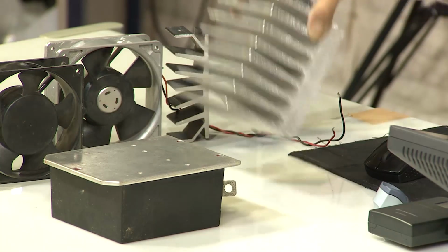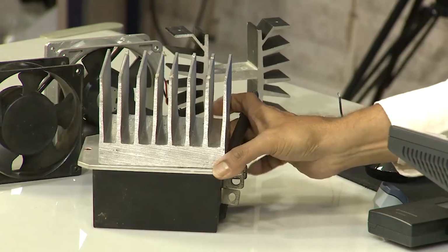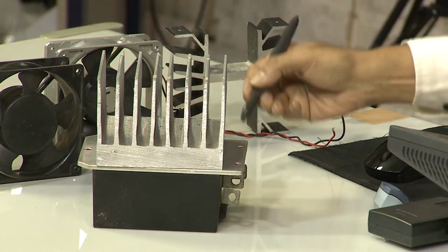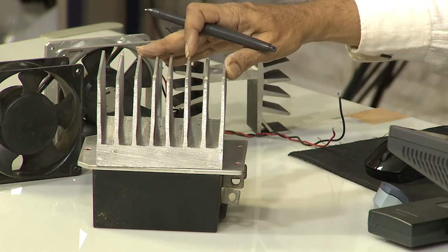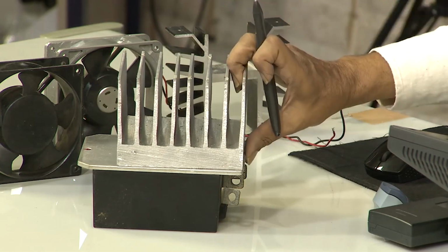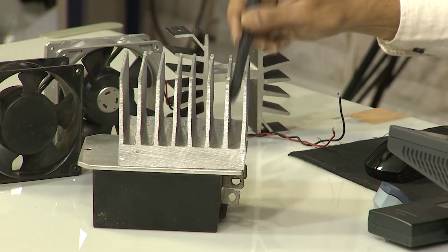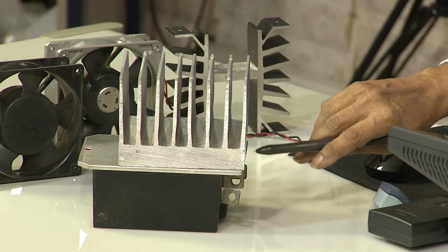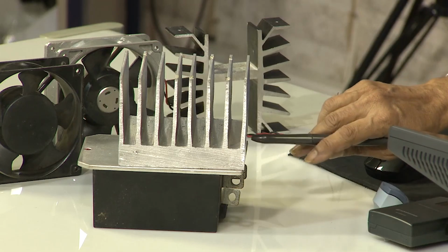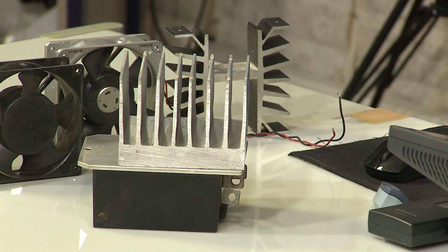Now, having known this data, we have happily put one on top of the other, and then I will find a way of how to clamp this and maybe put a flange or take the next higher size. Imagine this can be brought here, I can take the next higher size, match and drill holes, and put another plate which can distribute the load here, and then either tap this whole thing and insert what are called helicoil inserts.